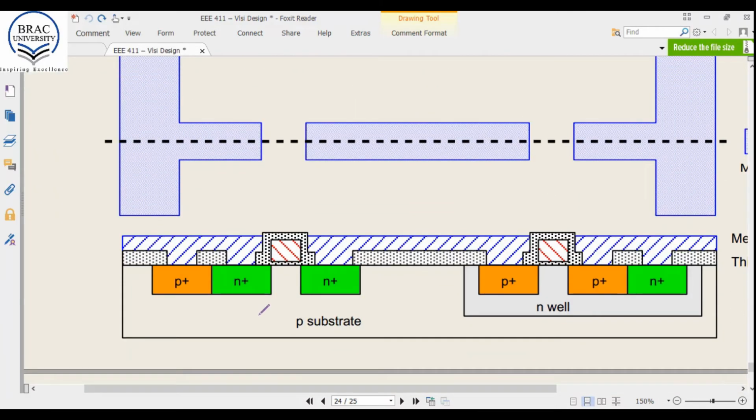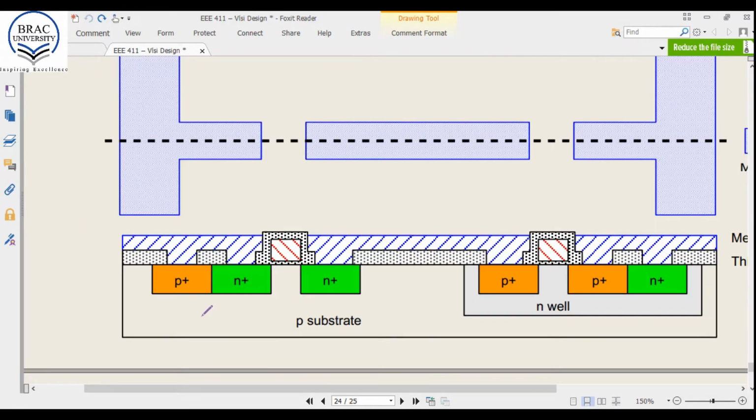First, consider this part here. We deposited the metal at this contact, and for this contact we used a titanium layer. If you have already used the software tool, you should know this metal layer, the first metal layer, is called M1, and this is a horizontal line, so I can call this part M1.